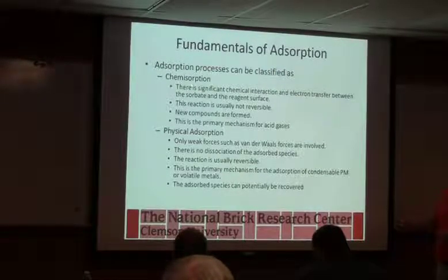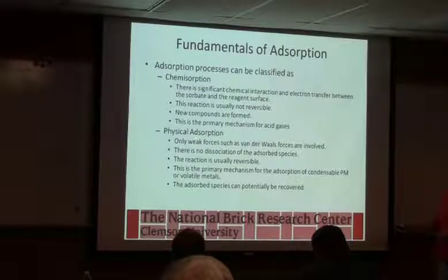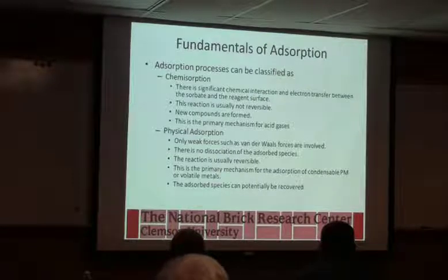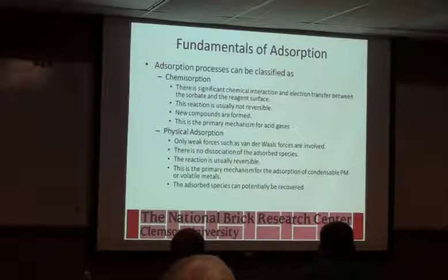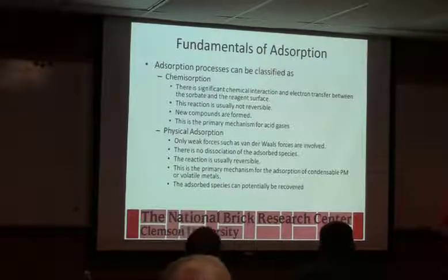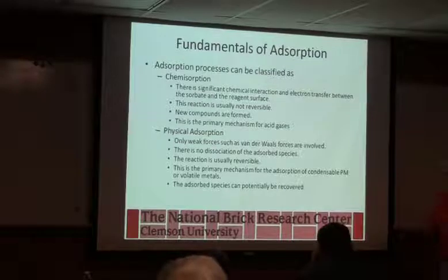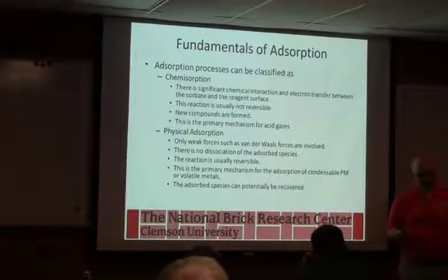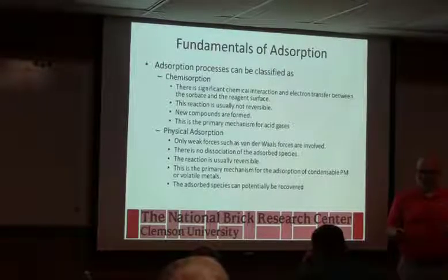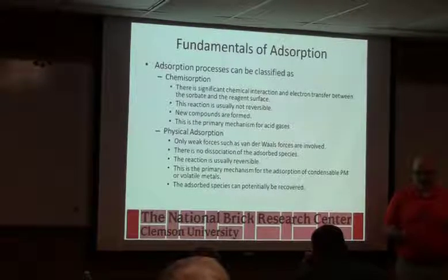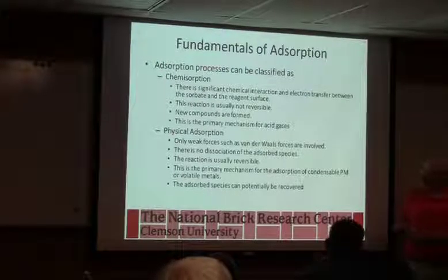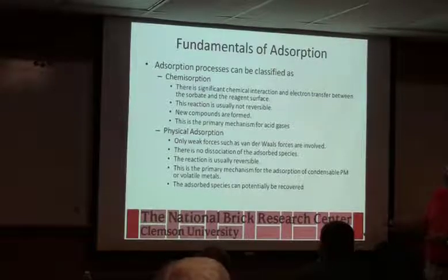So there's chemical absorption and then there's physical absorption. Some things like chlorine and sulfur, sulfur because of the size of the molecule and chlorine just because of chemistry, don't react as quickly as the fluorine. And you have to help them. So some plants, if you've got a dry injection system, sometimes you pre-treat it with water. The water helps to hold on to that stuff while it reacts. There are different ways of doing it, but it's a slower thing.